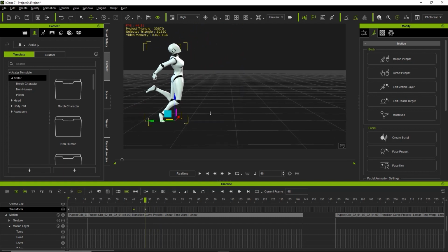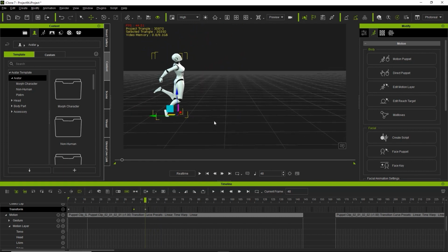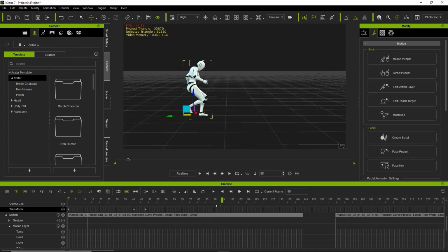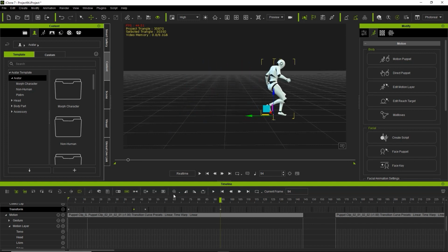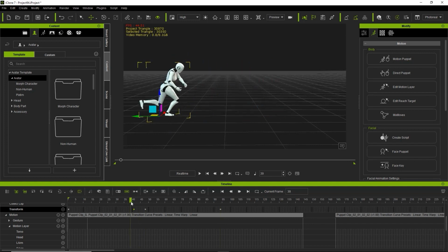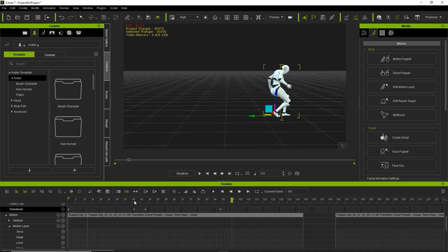So we've kind of fixed our jump. And for the jump, we just want to set 3 simple keyframes. The first keyframe we can set is how long we want this jump to go for. So if he's jumping like this, we'll kind of estimate, and here's where he lands, just like this. Okay, we'll throw it maybe a couple meters forward, just something like this. Okay, so what's going to happen now is it looks maybe like he's floating a little bit too much, so we can make it a little bit earlier.